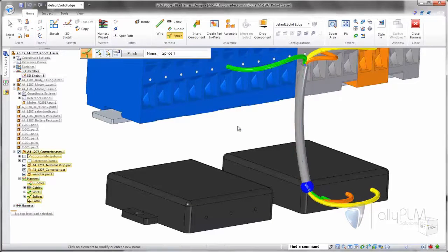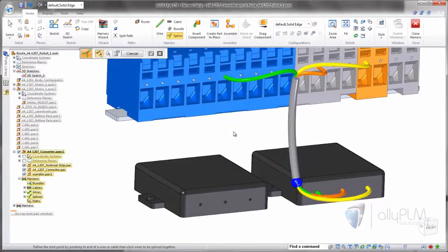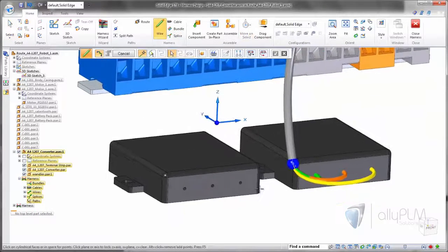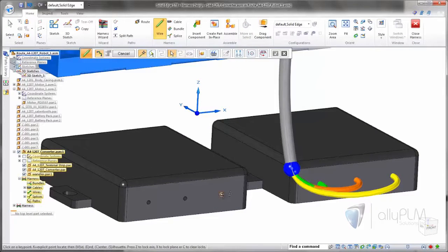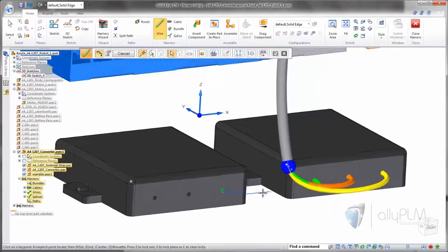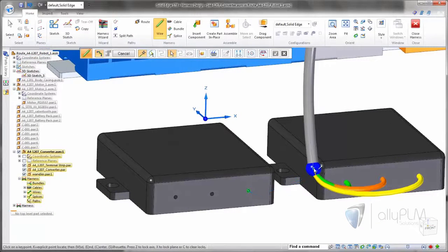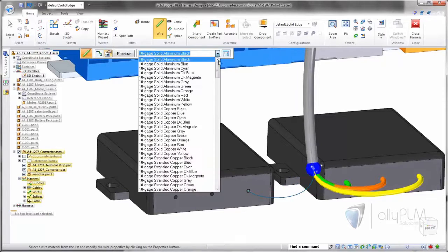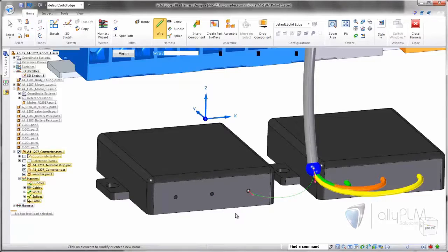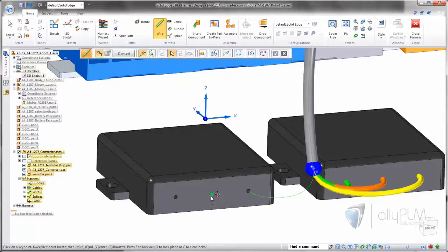There are several different splices available to be represented, and here we're just going to use a simple barrel splice. A sphere is created to represent the splice feature, in which we can now route new wires, or if the situation calls for it, even remove a wire. We can quickly place the wires necessary using our terminals for our anchor points and splice features as the endpoint. Quickly creating our wires to join to the splice, we've completed all of our necessary routing tasks.